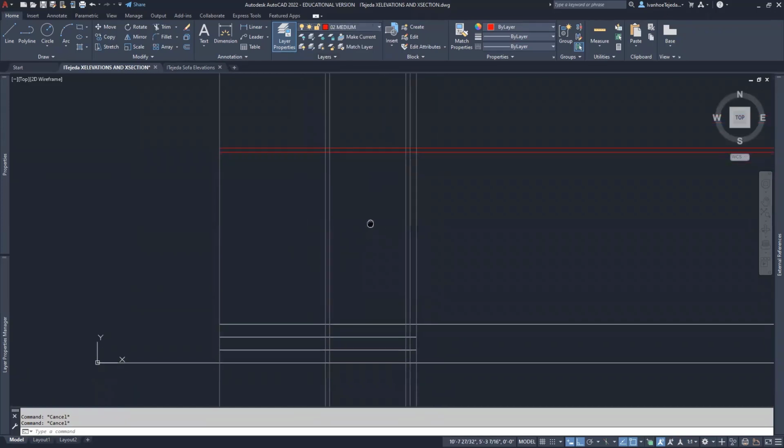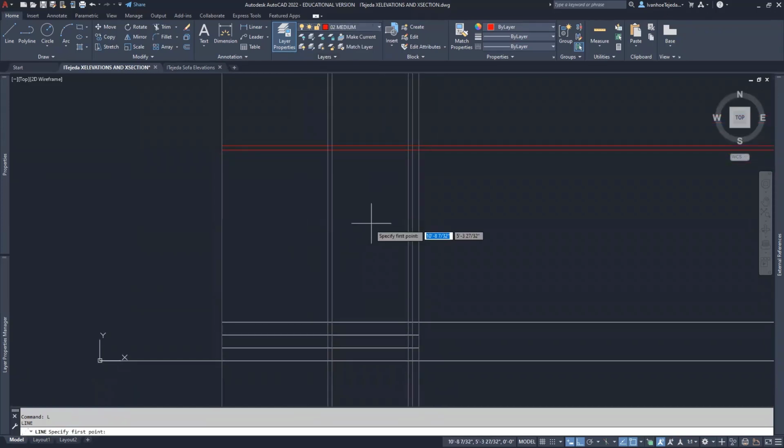And then I'll zoom out, and now I'll go ahead and draw some additional lines. Now I'm basically just tracing over the lines that I have in there, like this. I'm going to tap my space bar to terminate the command, space bar again to bring back the last command I used. Click here, take it down, space bar again, from here to there, tap the space bar, and then tap the space bar again, from here to there, and enter. That's the door.